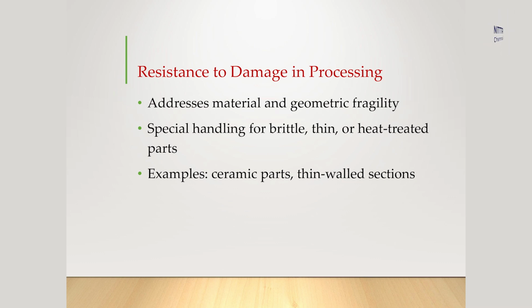Certain materials such as brittle ceramics, thin walled components, or heat treated metals require special handling to prevent cracking, deformation, or surface defects. Similarly, components with intricate geometries, sharp edges, or thin sections can easily be compromised if they are subjected to improper clamping, excessive cutting forces, or inadequate support during the machining process.